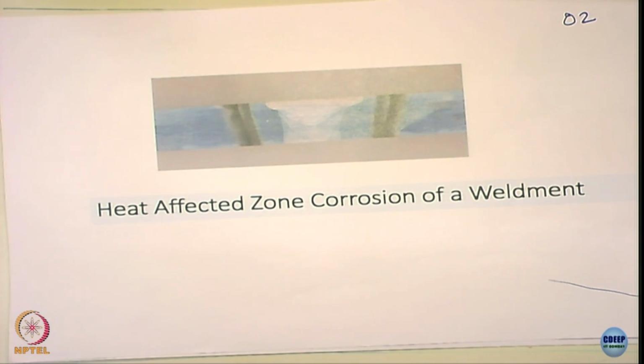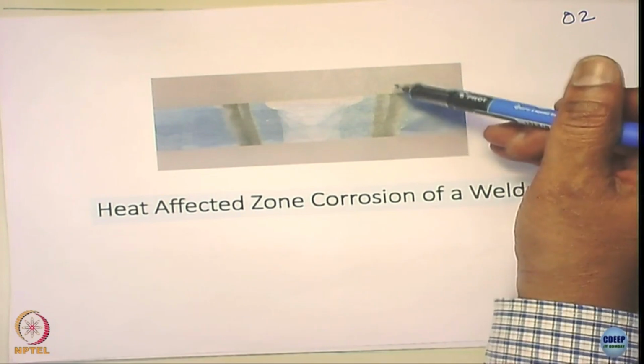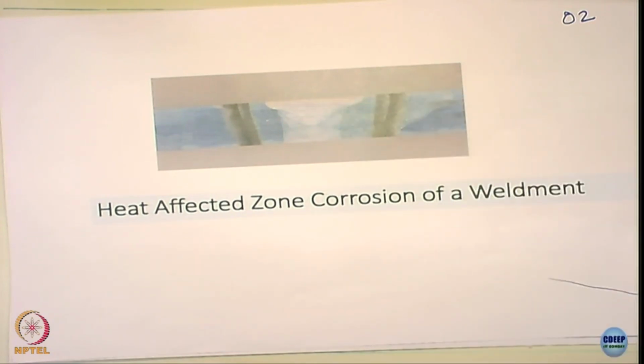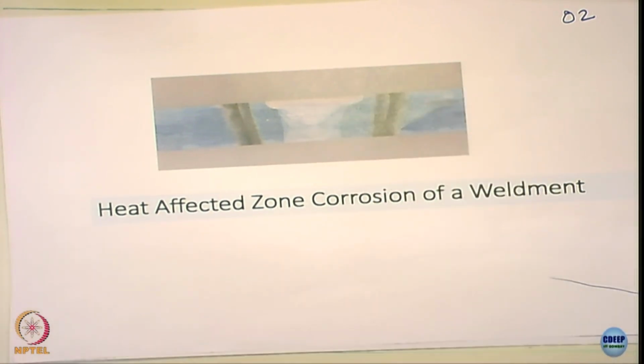You weld a stainless steel, and what is this? This actually is a TIG welding, and it's a butt welding, right? It's a butt joint, right? What do you do in a TIG welding? You strike an arc, right? And you use a filler wire. An arc is struck between the metal and the electrode, right? The temperature is so high, it melts. It melts the electrode, either it's a consumable electrode, for example, or you use a filler wire. It melts, and then they deposit and they join. That's how you do fusion welding.